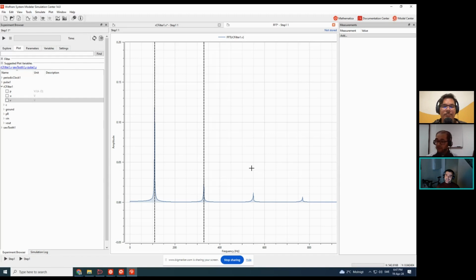So Leo, so Vedat, as you mentioned, we saw the detailed model of a gearbox yesterday, right? Imagine there is a failure in one of the teeth in the gearbox. When this failure point arises, there is some event that is triggered, and since it is rotating, there is a frequency involved, right? Looking at those frequency curves, perhaps we could figure out which tooth is broken, from vibration analysis. Those kinds of things come to my mind. Perhaps you have a different picture, you have a different story.